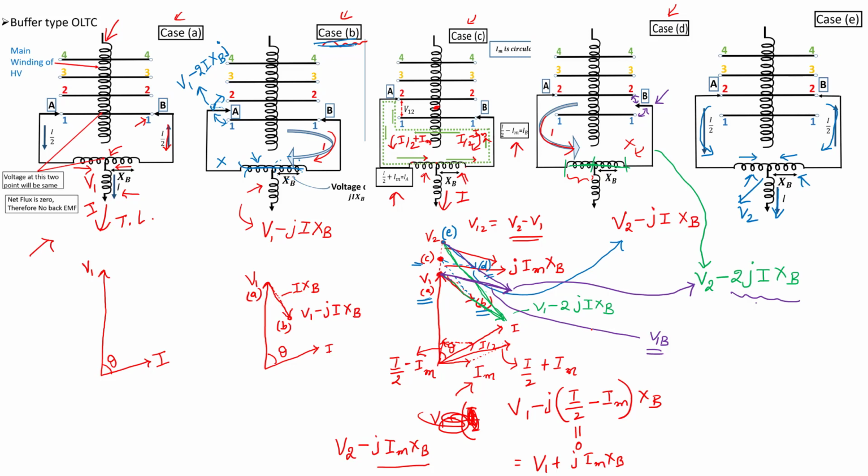And one more aspect here, when the half of the winding is there, suppose the full winding reactance is X, capital X, full winding reactance. The half winding reactance is here. What is happening here? So you are not changing the core. The core remains same. So simply inductance is N square by R. So simply number of turns is becoming half.